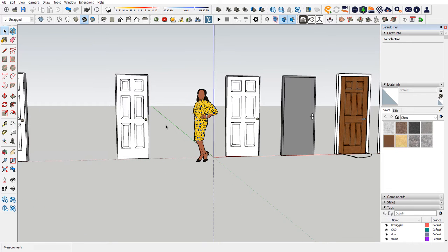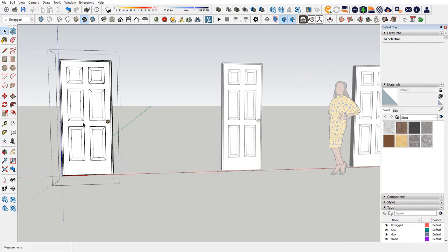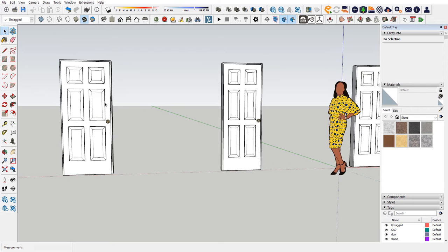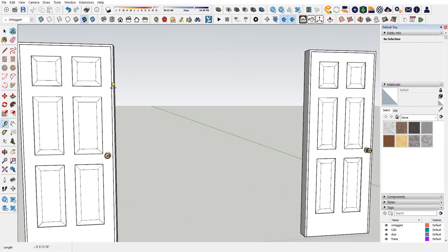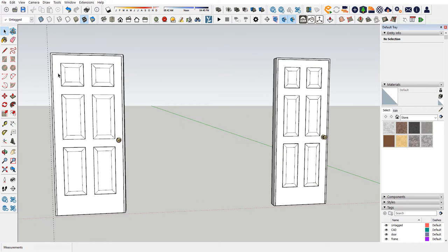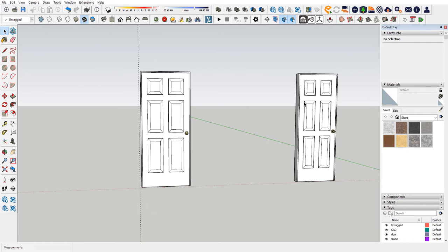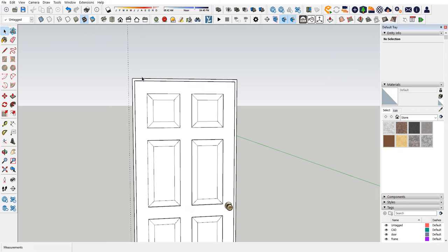This is a 2'10", 2'6". What if it's supposed to be a 3-foot door? All right, kind of the same situation. Double click. T for tape, well, let's go back. I do the tape measure outside, let's say. T for tape measure. Click here, come across this way in the red. Type in 3 foot. There you go. So the door has to be that wide. So in this case, I probably will do the frame first. In this one, I did the door first and put the frame to it. This I'll do the frame first and get the door to it.